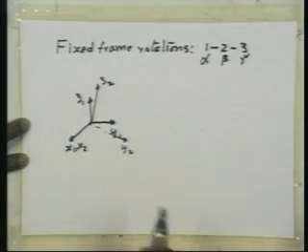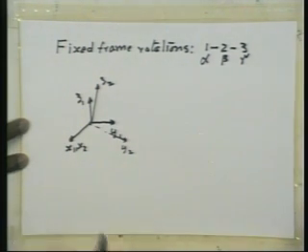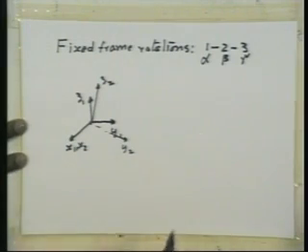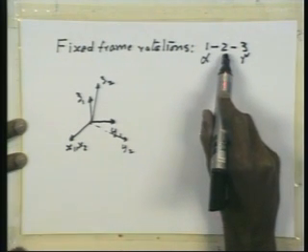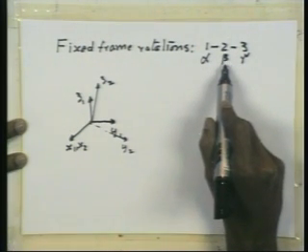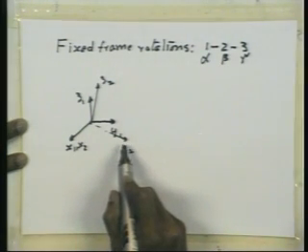Fine. So now here, which is the global reference frame and which is the body reference frame? Yeah, x1, y1, z1 is the local reference frame now. x2, y2, z2 is the global reference frame. Fine. So this way I need to use just one figure to show all the axes. So now I look at the next rotation, which is about the global y by angle beta. So global y is now y2. I rotate that by angle minus beta instead of beta.